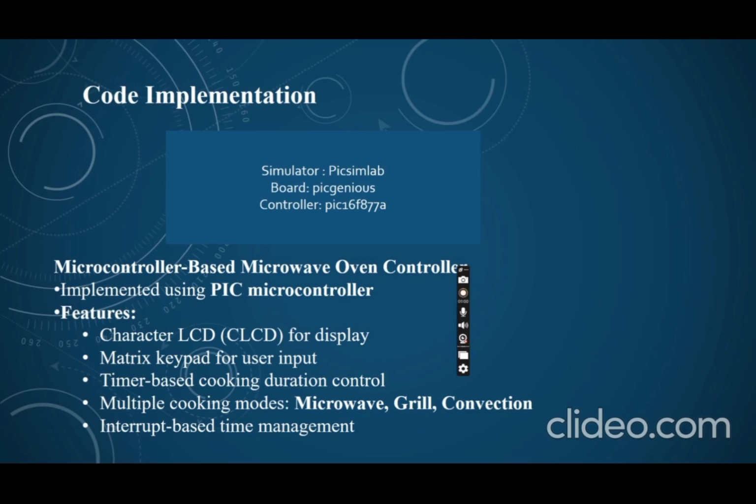Timer configuration sets up timer 2 to generate periodic interrupts, which are essential for time-dependent operations like cooking duration and preheating. We also used microwave and main.c to write code, and the CLCD and matrix keypad files were given by Emertxe, downloaded using the Emertxe Moodle app.